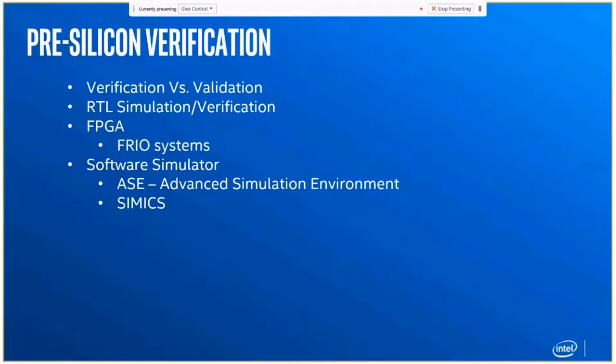So exactly, going back to that same DPI thing, when a packet comes in, it does a scan, and then when it sends out, it's actually a C code running on a Xeon processor or something, right? But depending upon the packet size, what came in and how it actually processed it, it can compute in the code itself how many clock cycles it would take in the real CPU, in the real silicon, right? And it can provide that as statistics from the block, right?